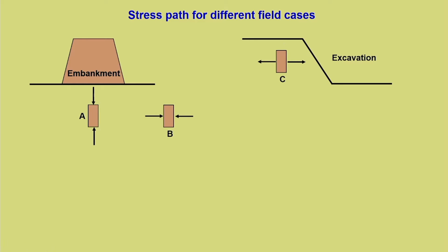Now, axial stress is the same and the radial stress is getting released, meaning it is a typical compression that we discussed in the lecture that we dealt with the laboratory triaxial testing. Now, case D is a case where lateral stress remains the same, but the axial stress gets released. So, that is also a typical case that we have discussed, and that creates a kind of extension.